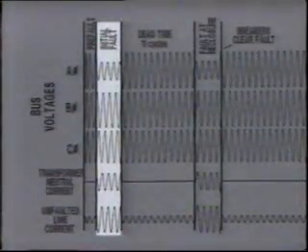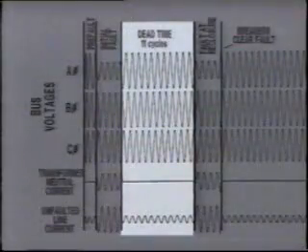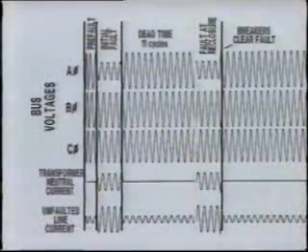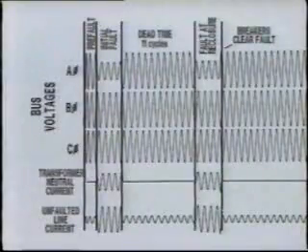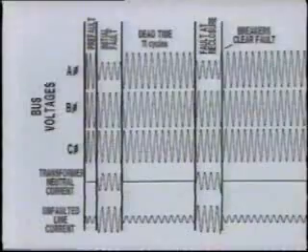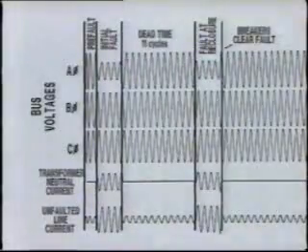We can also tell that the fault duration is 4 cycles, and the line dead time is 11 cycles. At this point, the breakers on the faulted line reclosed, but the fault was still there. So the breakers immediately tripped out again and locked out. If this problem repeats itself over a period of time, we may conclude that 11 cycles of dead time is not enough to allow the temporary fault to deionize and dissipate. In this case, the dead time would be increased by changing the time delay at the breaker.